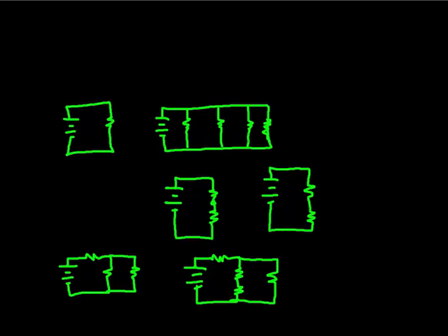This gets a little more complicated here, but same premise. If you have 12 volts here, and there's 12 volts potential sitting here, then assumedly the other end of this is at 0. That's how you get the 12 volts difference in potential. Well, that's a solid wire. So guess what potential is sitting across every one of these resistors in this circuit? There is 12 volts. So if you knew the resistance value of each of these, you could simply do I is equal to V over R, and you would know how much current is flowing through every one of these resistors. But it's simple enough to know that 12 volts exist across this whole entire circuit, because we cannot remove nor create energy in a circuit.